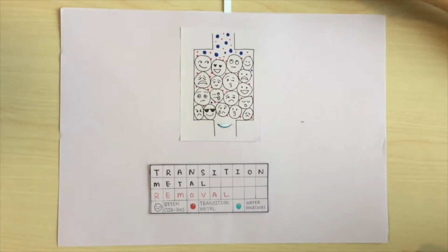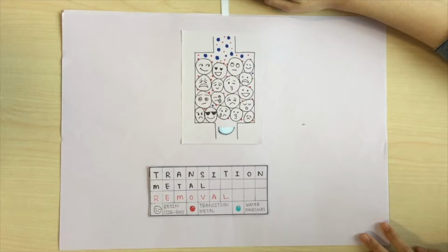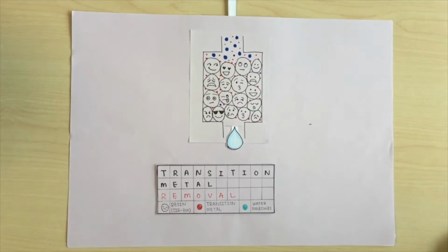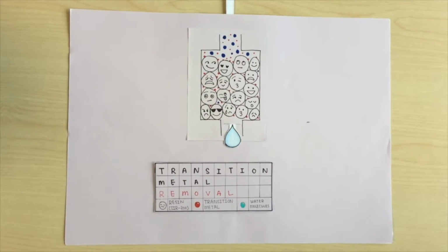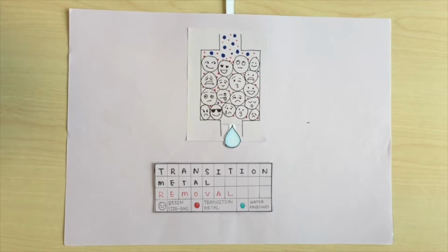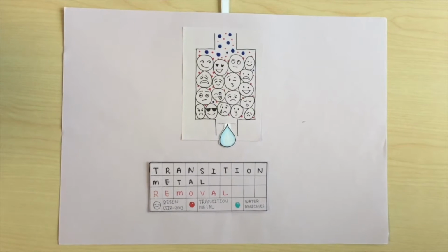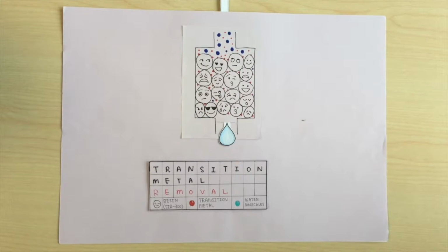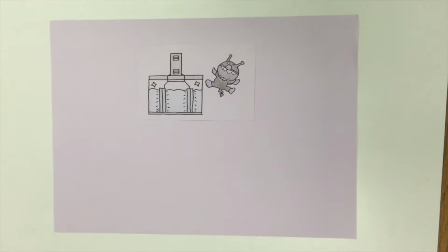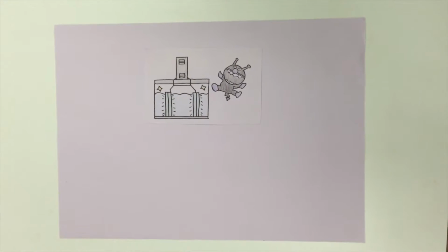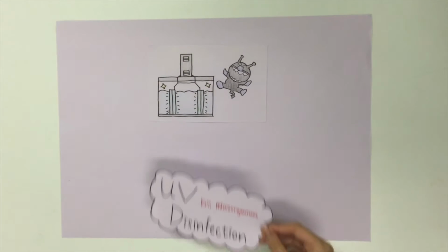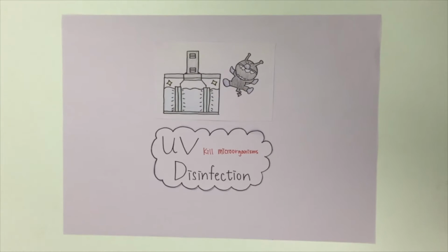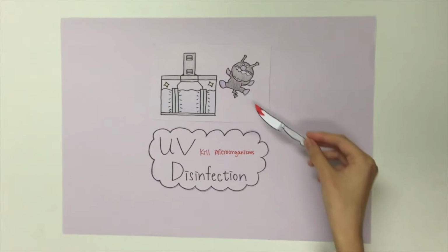by ion exchange. The resin that we use is SIR 300, which is a sodium-form macroporous chelating weak acid cation resin. Also, the pH value should be set between 1.5 and 14. Finally, the temperature should be set below 50 Celsius. After removing arsenic and transition metals, we need to kill the microorganisms. Microorganisms are killed in the UV disinfection system.